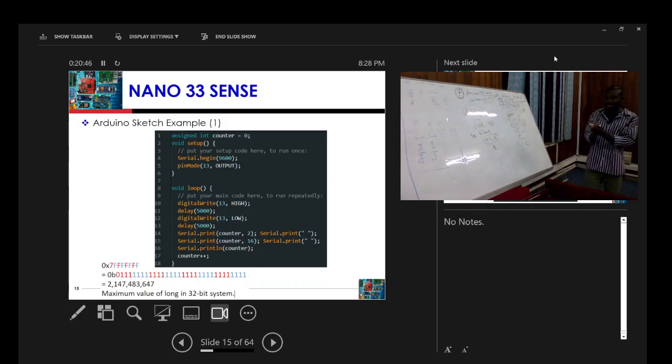So you see that if the number is unsigned, I can use the entire thing to find the highest number. At first it was 1111, which was 15, right? So the highest number of an unsigned number is the whole thing, which for this 4-bit is 15. If it is signed, the highest number will be 7. So it has cut the range by half. Understood? 15 and 7. There's no course for this, so you can go and study it somewhere and refresh yourselves.